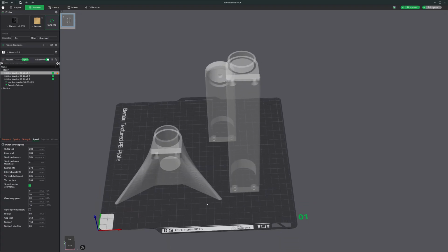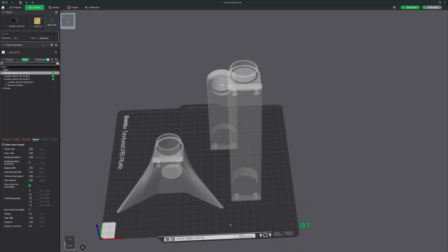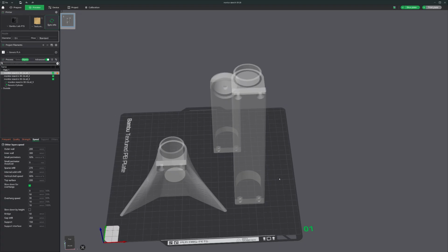The reason why this is important is because the taller your part gets, all of this is wobbling a tiny bit. The printer's trying to compensate for it, but there's a certain point where it can't compensate anymore. So you would find out what layer height that is by measuring it out, making a modifier, how I showed you before, to find the right height using your slider on the side and setting that modifier.